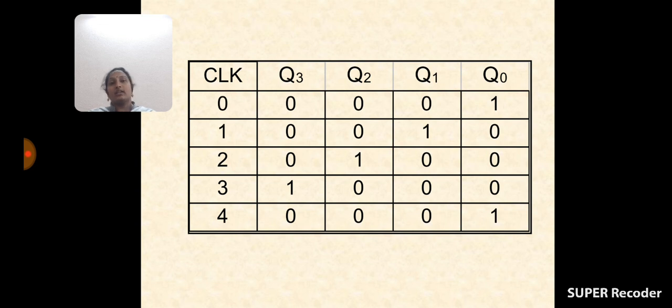But in all other synchronous and asynchronous counters, for the initial clock pulse, the outputs of all flip-flops are 0. But here we directly apply the preset, so that for the first clock pulse the first flip-flop will produce the output. So that is the main advantage here.